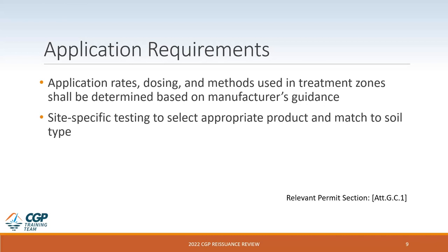And again, what that'll do is allow for the most sediment to be bound and settle out, while also using the least amount of chemical on that site, which again protects water quality and limits the possibility of accidentally discharging unbound chemical from the construction site. So site-specific soil testing is an essential step early on in this process.